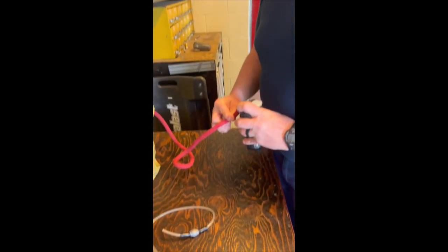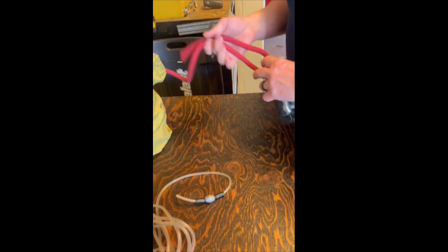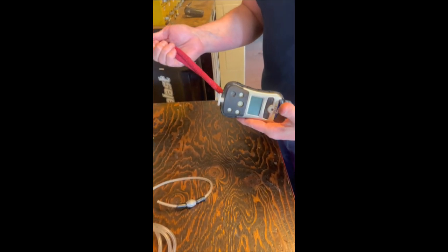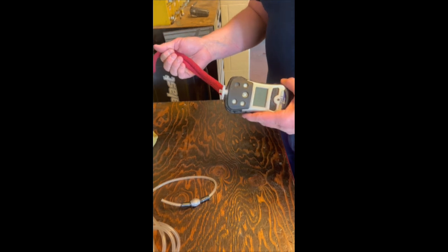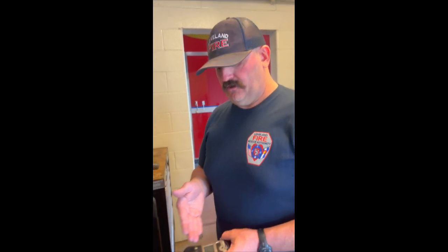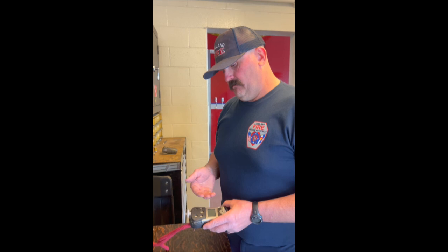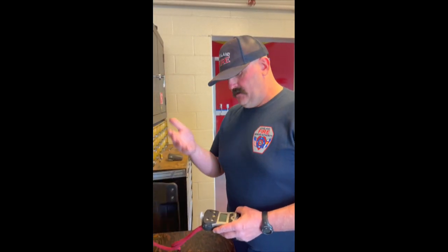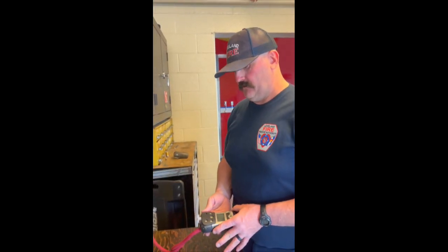The other way, with the monitor running, is to tie the monitor off to a utility rope and lower the rope into whatever space you want to monitor. And then two things. You would know if it goes into alarm that obviously there was an environment it would be alarming for, but you may not know exactly what because you're away from where the monitor is and you can't read it. And even if it does not alarm, we can still use data from the monitor to tell what the environment was throughout the time we dropped it and then brought it back to the surface.